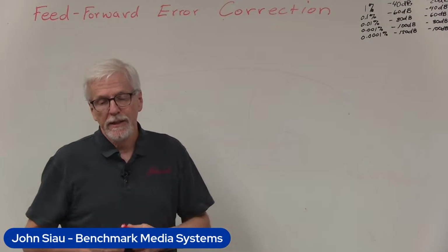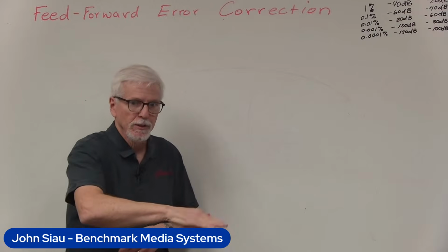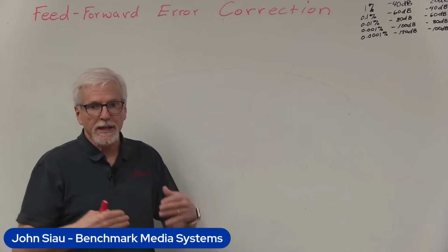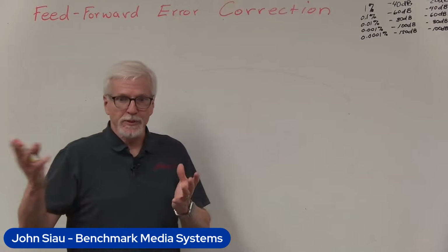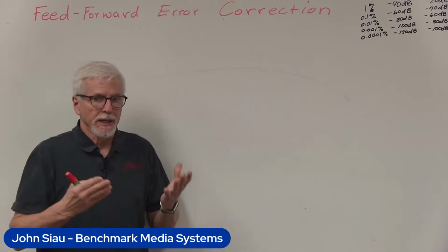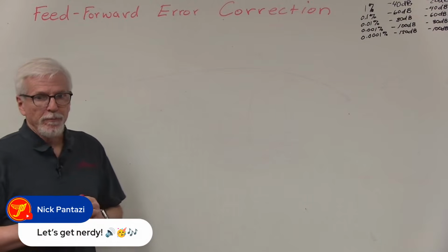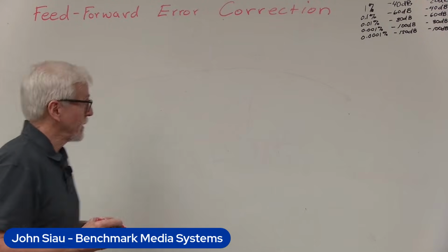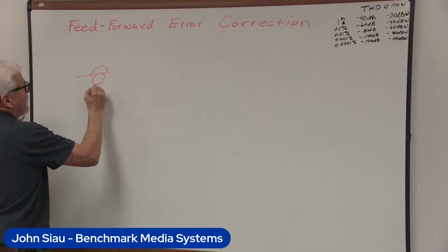We set the thermostat at a certain temperature, and the temperature ramps up, and it overshoots a little bit, and it comes down a little bit, and eventually settles out. And depending on the location of the thermostat, depending on the location of the heat vent, the heat coming in from the sunshine, all of these things can influence that feedback system. Sometimes they work very well, sometimes not so well. So to illustrate what a feed forward and feedback system are, first of all, let's imagine we've got a firefighter,